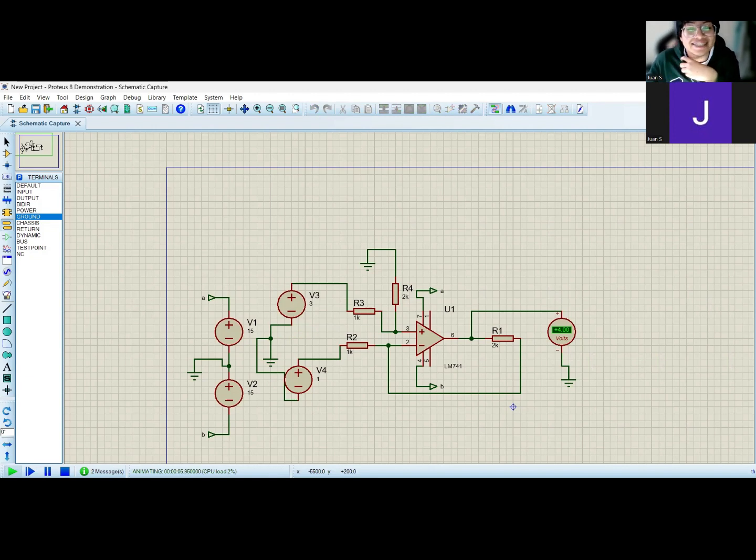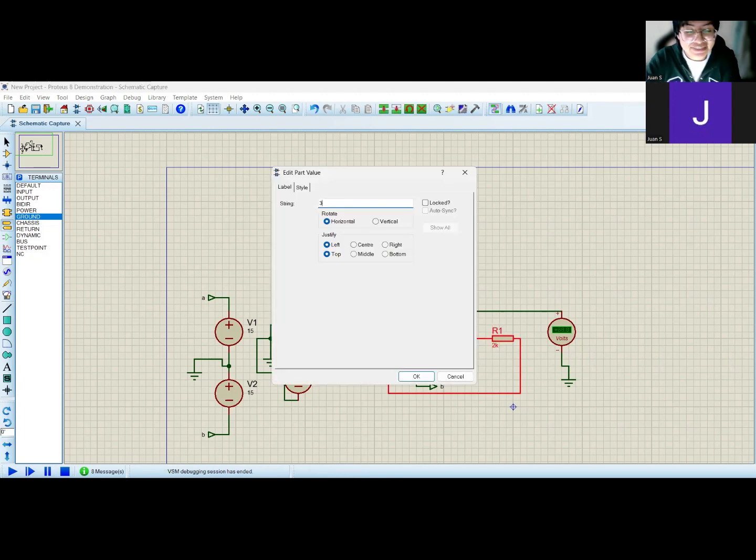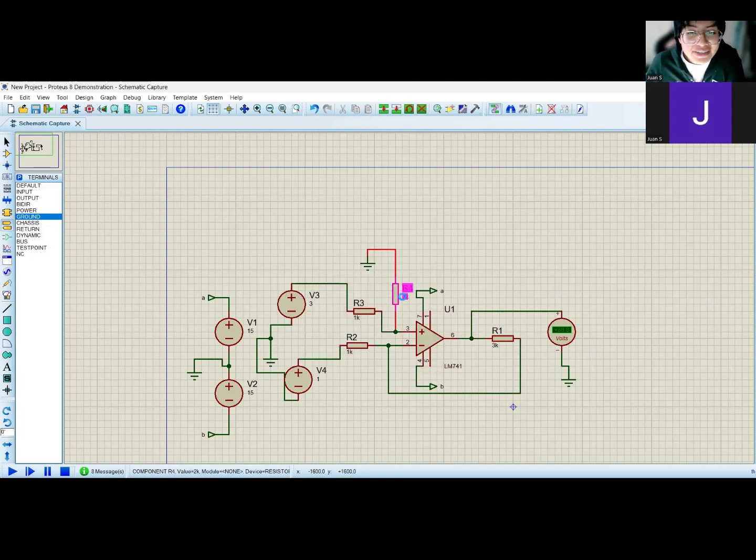However, I committed the mistake that this could be 3K. So let's replace this very quickly. 3K and 3K would be 6 volts. Now it gives 6 volts; I committed a mistake, so sorry. So as we can see, this configuration can work both as an amplifier and also as a subtractor. Depends on what you need. You replace the resistances according to your needs.